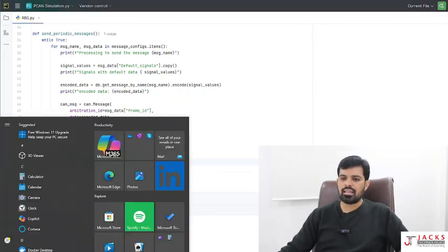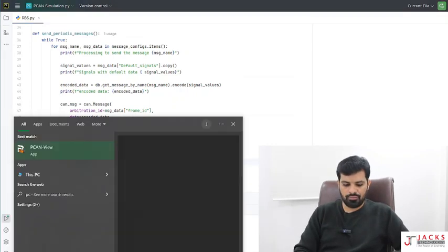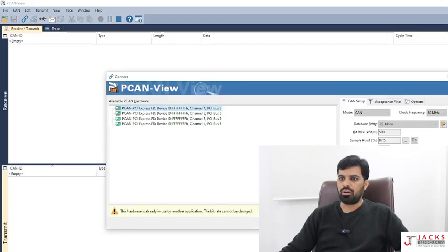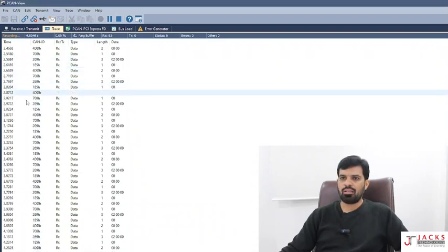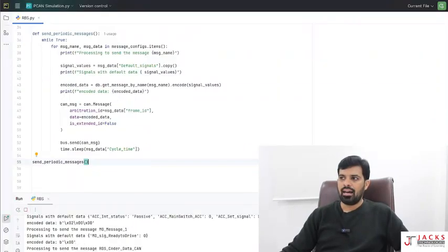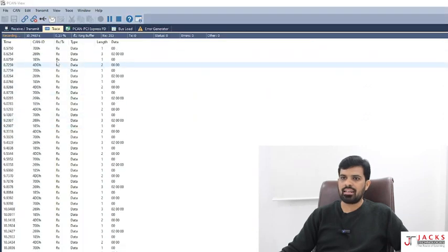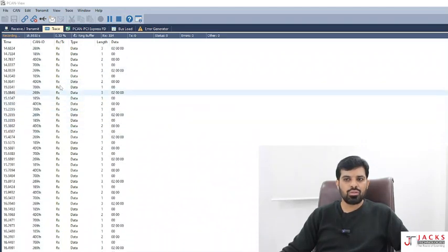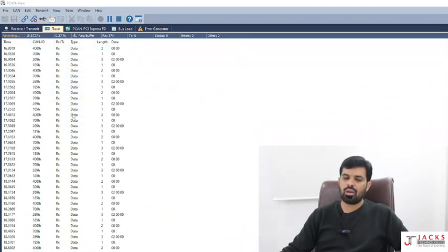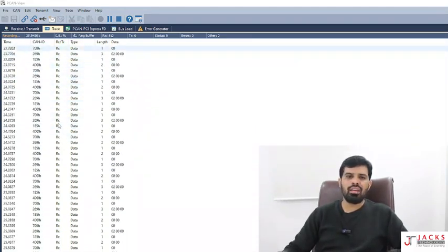Guys, let's check whether our messages are flowing over the PCAN successfully or not. I have just opened PCAN and I have taken channel one. See, the messages are flowing. All the messages are flowing with the proper periodicity. Whatever I have transmitted through the Python file, all the messages are getting transmitted in the PCAN view. But you can see all the messages are shown as RX, so you should observe it as TX. Right? This is a different story and a very big story.